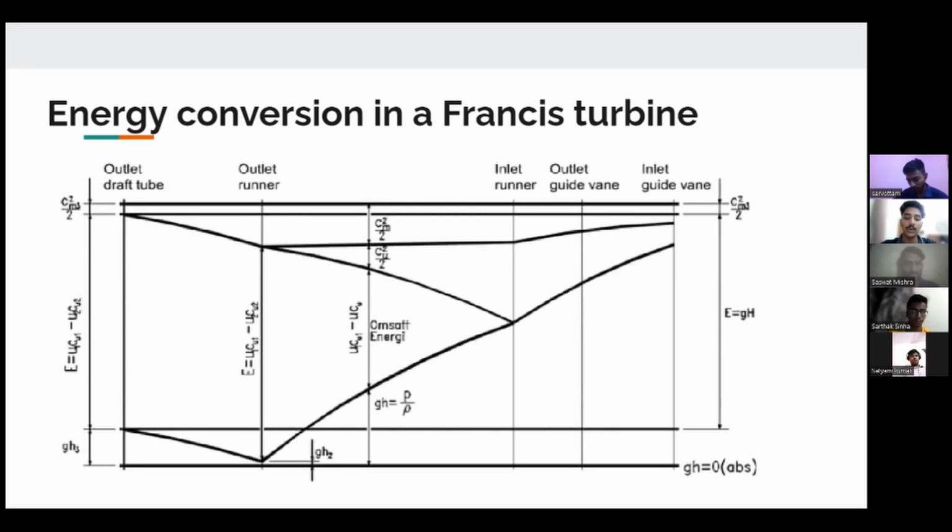In this case the rotational energy increases to match the circumferential speed of the runner blade. Also, the meridional velocity increases because the water is flowing towards the decreasing diameter. As a result, the pressure energy decreases up to 50% of the total energy at the inlet.